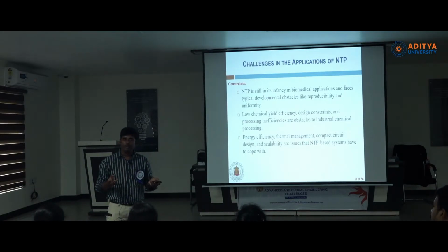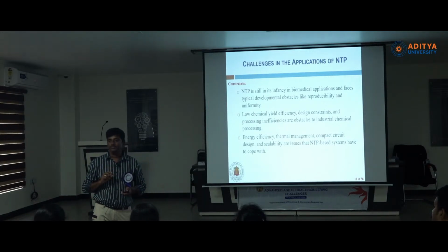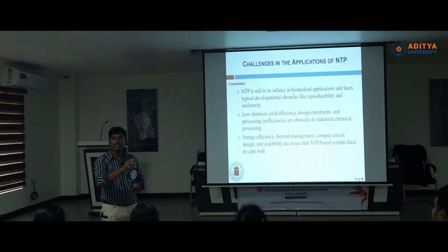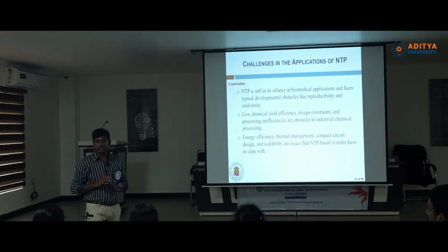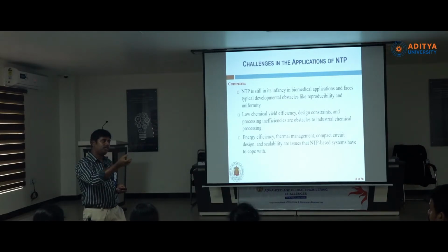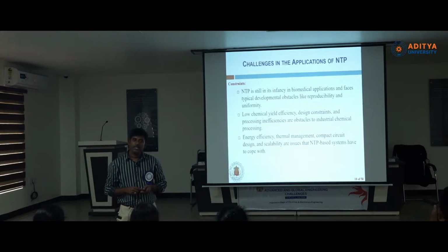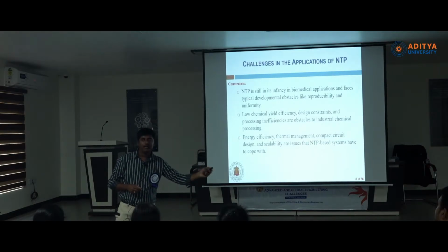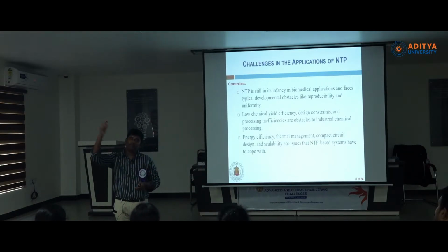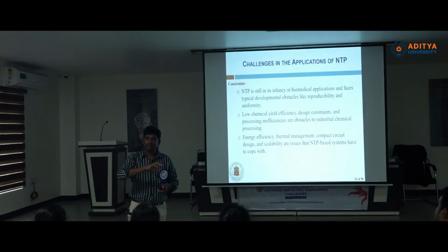The advantage is that we need not have much current. Current value can be in milliamperes itself. So power is not an issue for us. Power of 10 watts, 15 watts is also sufficient for us, because the reactor is treated as a capacitive load. So from a 12 volt battery itself we can just step up the voltage level. When voltage increases, current decreases, that is not an issue for us.